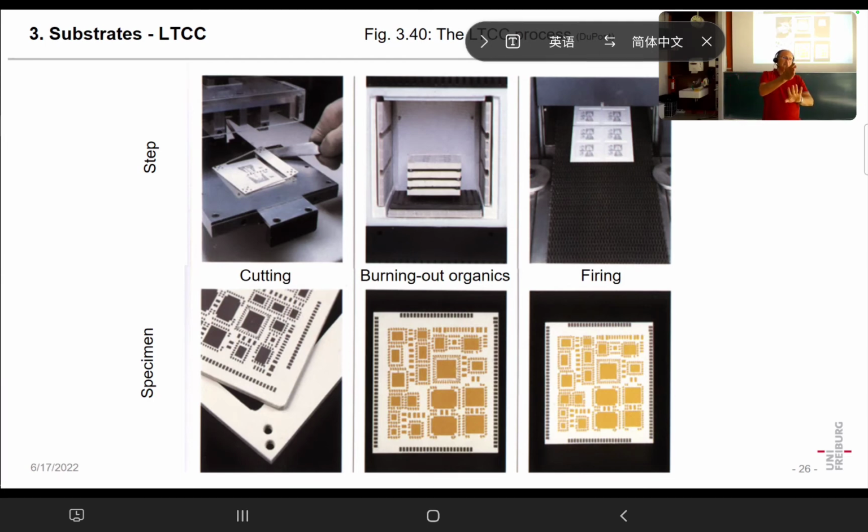That device has a certain pitch, yeah? And when you fire and you reduce the size, for instance, it can shrink, let's say around 10%, yeah? That must be precise, especially for big devices, because what happens if I have on the one side this pitch and on the other side this pitch? So it doesn't match anymore, yeah?